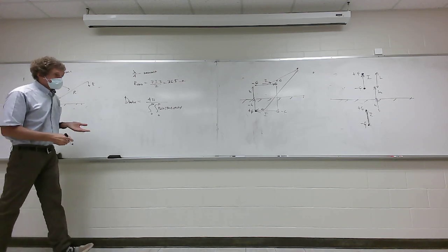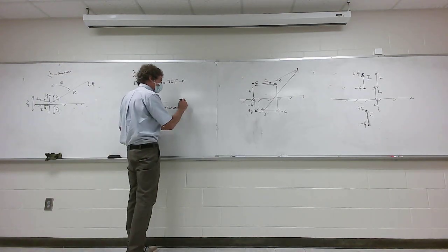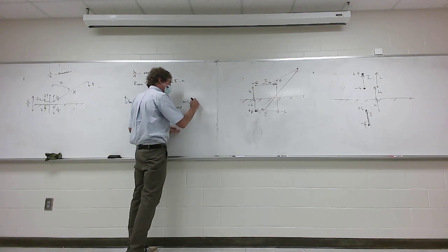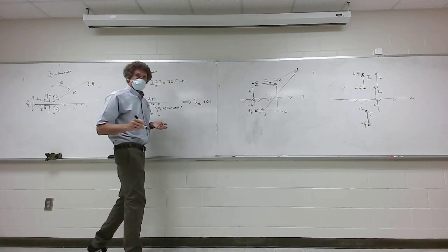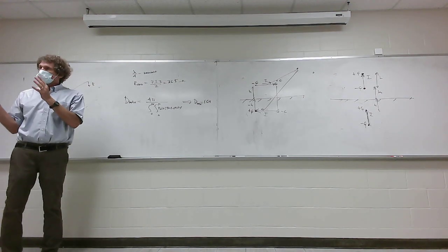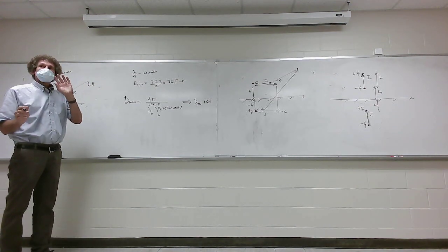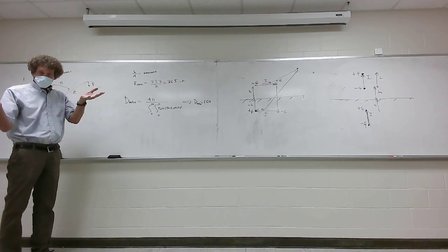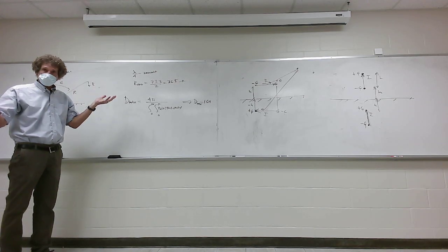And I know if it is a half-wave dipole, this D max would be equal to 1.64, right? Now, hear me. If the current is the same on both, you're going to talk about normalized power, so it becomes an irrelevant point. You want the angular variation, correct, class?